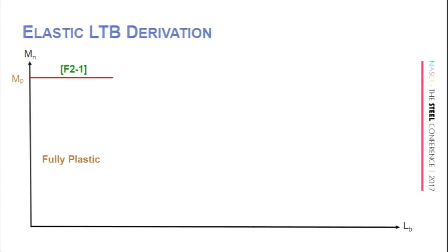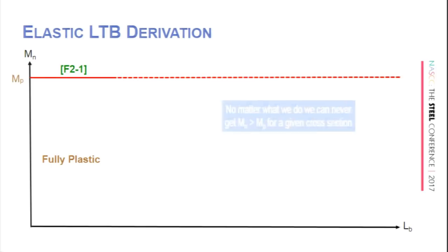That's where we would like to be, but how many times do we say this is the critical beam in our design and we're going to use that same beam so the fabrication gets easier? So not every beam is ever going to see that full load. So really, where do you need to be on the vertical axis? Well, you have one critical beam member that you need to design and then you sort of replicate for your others, and probably the rest is okay by inspection. So how do we get there?